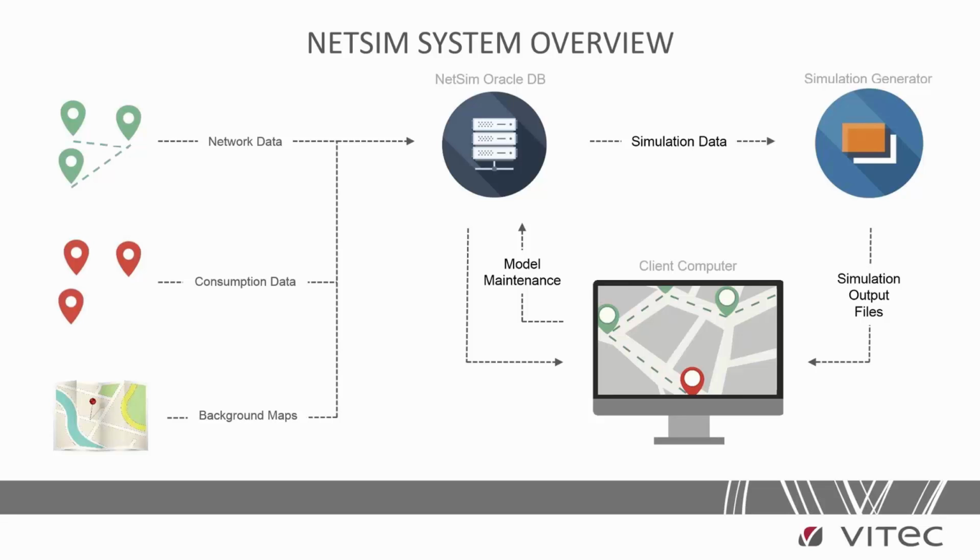So you can say that NetSim is two different modules, one for maintaining the model, and that means that you could add a customer or change a pump setting or something like that, and one part is the analyze part when you have done a simulation. As you can see, we have the simulation data from the Oracle database into the model, and then we will have an output file that you can view. That's a file that you store for as long as you like, so you can have different scenarios that you already have made simulations for that you can bring up after 6 months or whenever you like.